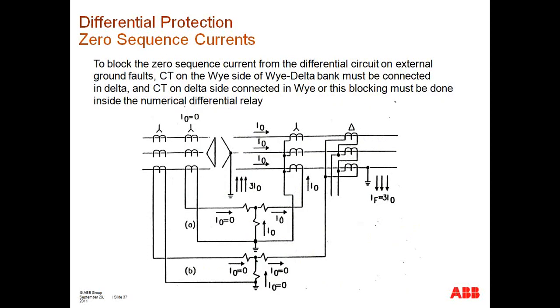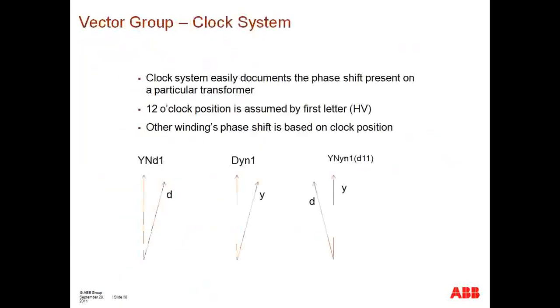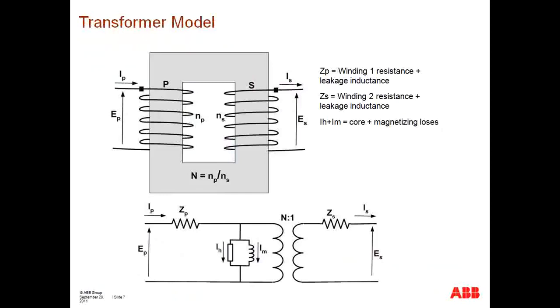Inrush current. So when looking at inrush, I'm actually going to come down a couple of slides to provide you with this explanation. So if we take a look at this basic circuit model, what your inrush currents concern is, I'll explain it in a very practical way. Okay. Imagine that you have a source connected on this winding right here, and there is absolutely nothing connected on this winding right here. If you close into this particular winding, although there's no load connected here, you have this magnetizing branch through which current is going to flow. That, in essence, is your inrush current, which, if we look at the way we apply our differential protection, there's going to be current that's going to come through winding 1 CTs.